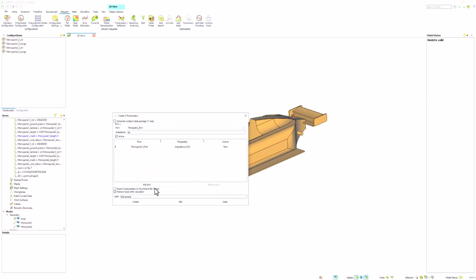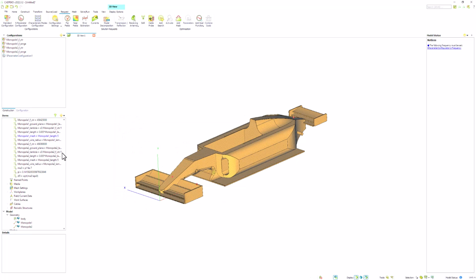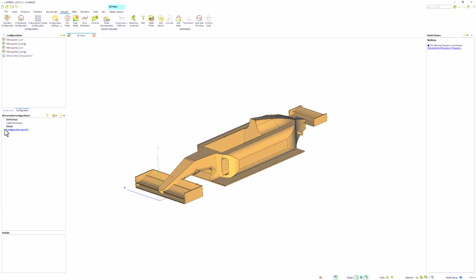Now we can define the request for the model to solve. By using the component library, we already have configurations and requests for far-field data. However, we can also create an S-parameter request to analyze the performance of our antennas as one multi-port system on the race car. We can define how to space the measurements in this analysis based on our specific needs.